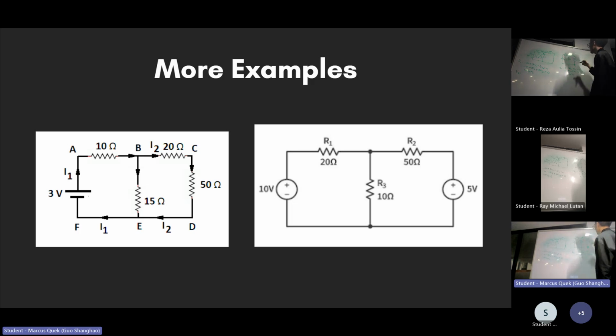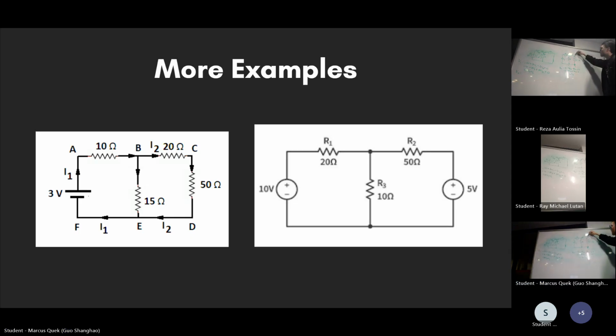It's a bit confusing, but as long as you follow the convention that current goes in for resistors, you must put the positive sign where current goes in. The way you know what the current direction should be is you look at the potential difference at each point.